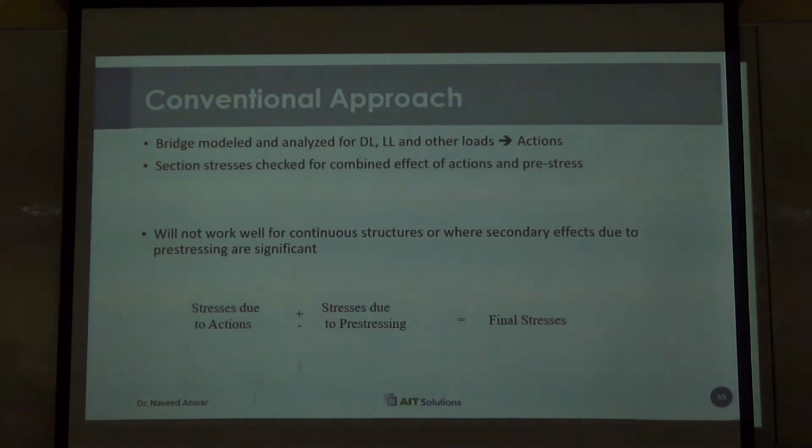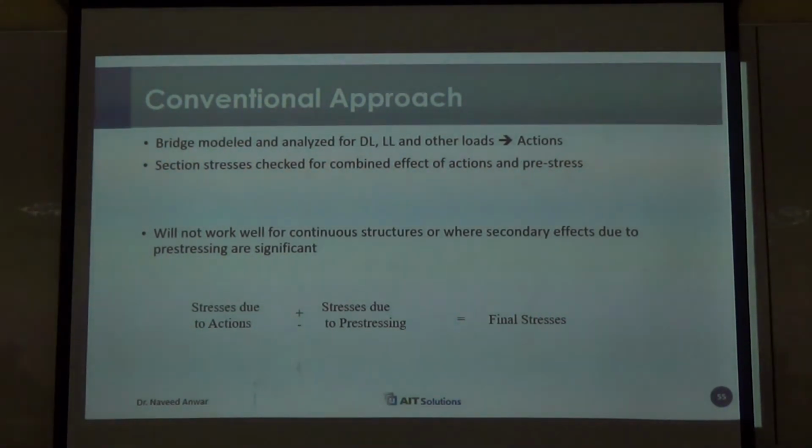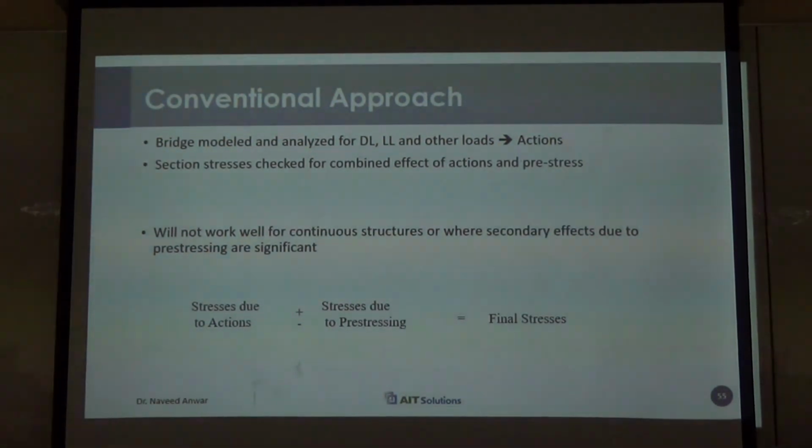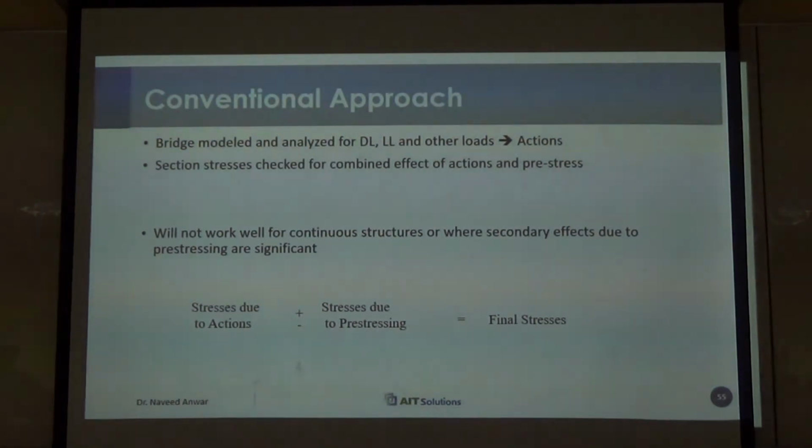Conventional approach is that the pre-stressing is considered as part of the design as a reinforcement. But actually pre-stressing is really a load on the bridge or on a girder. It's not a reinforcement. It's also a reinforcement at ultimate stage, but at service level, it's a loading. And that is very important because it changes the stresses in the whole bridge. So if you have pre-stressing, you will get different moment. If you don't have pre-stressing, you get different moment.